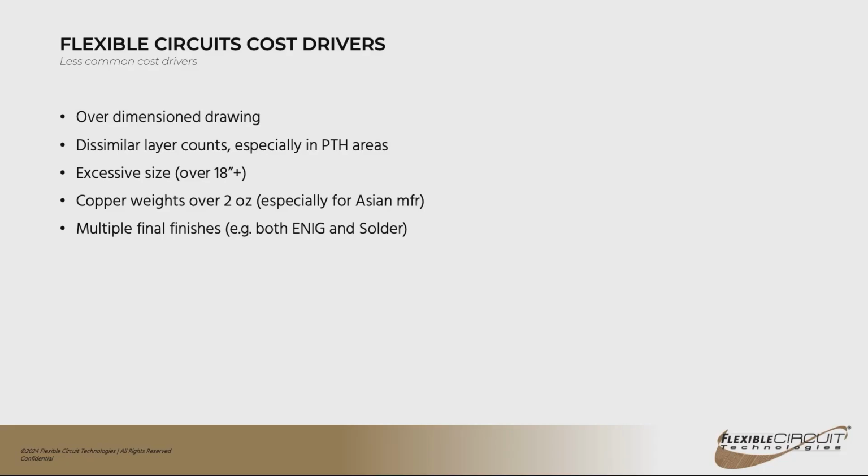As far as the standard panel sizes, every manufacturer has different panel sizes. In the US, I can tell you that 12 by 18 is common, 18 by 24 is common, 12 by 24 is common. With flex circuits, the bigger the panel, the more difficult it is to process them, just because the material is so dimensionally unstable. It can grow and shrink by up to 1 mil per inch just with temperature and humidity.